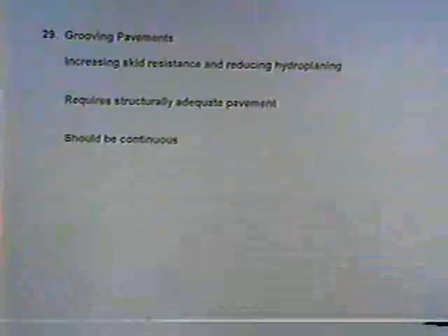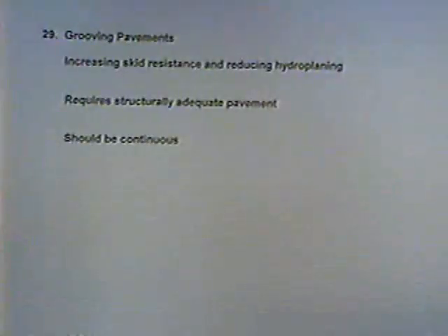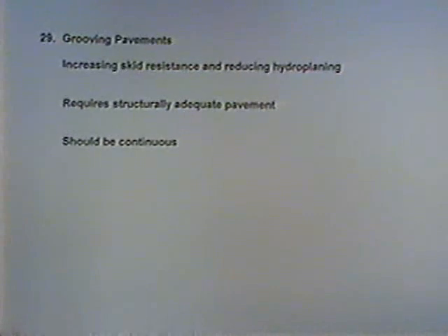There is some information about grooving pavements and how and why you do it, in terms of advantages and disadvantages. With grooving, we're really cutting grooves longitudinally in the pavement surface. We do it to increase skid resistance on slick pavement surfaces and reduce hydroplaning. It basically gets the water away from the surface of the roadway so that the tires can make contact with it, increasing skid resistance and braking capability.